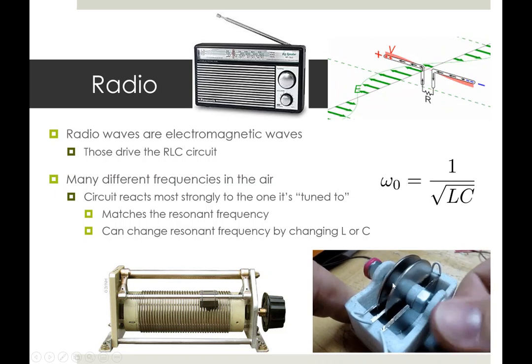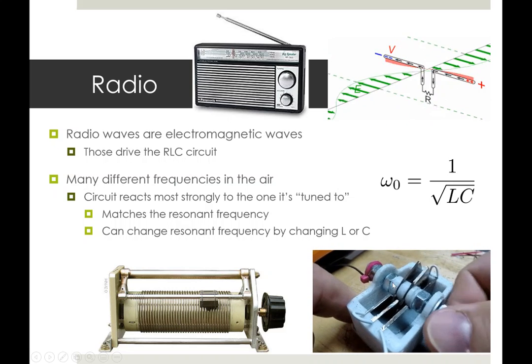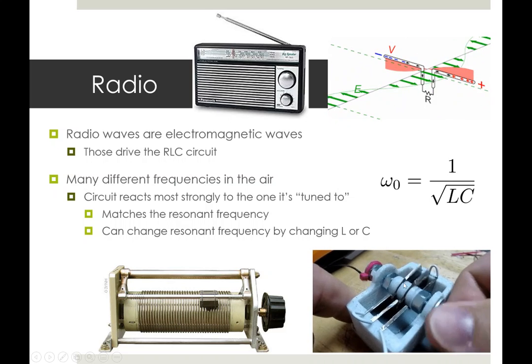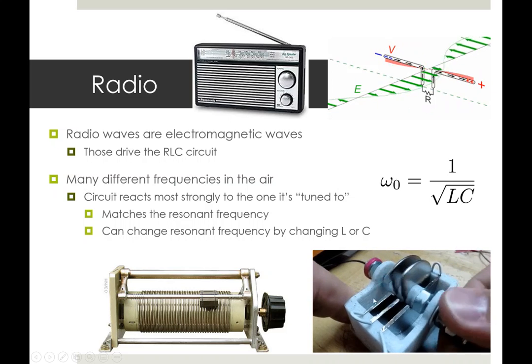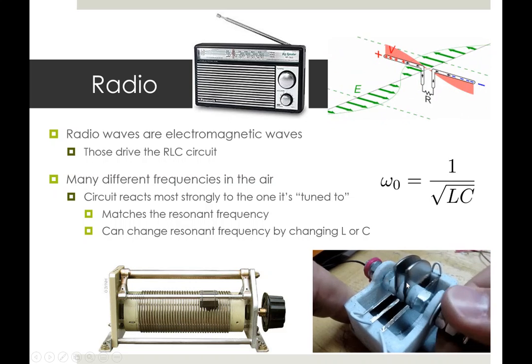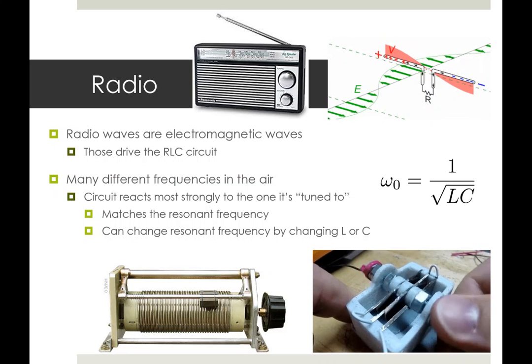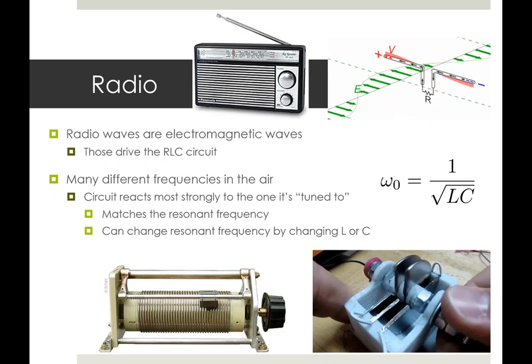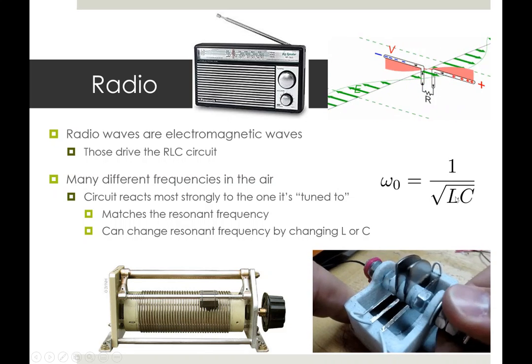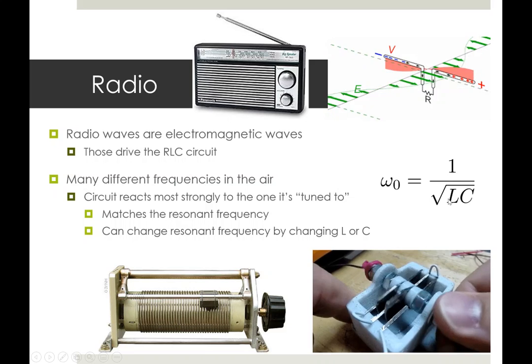And what's being shown here is what that looks like from an engineering perspective. What you're seeing here in this animation is a variable capacitor, where by sort of moving the capacitor plates around like this, you're sort of changing how close they are to each other, in effect kind of changing the D in epsilon A over D, which is allowing you to sort of tweak the capacitance, to tweak the resonant frequency and the quality factor as you go.